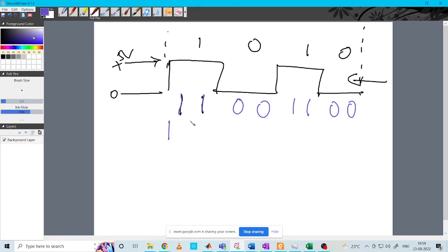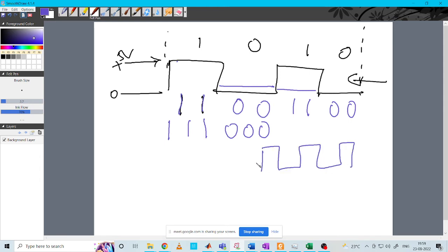Someone might say that it is 111000 because you do not know how many zeros are there, right? Correct, sir. There are no clock cycles. Correct. So unless I tell you the clock cycle and the bit width, never answer in real life or in some real world problem. Whenever you see a wave like this in a CRO, do not consider that as 1010. It can be 11001100.